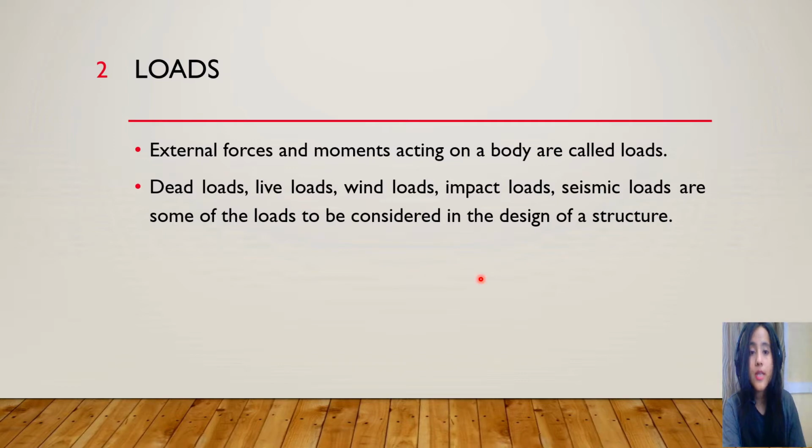So the types of loads acting on a structure, for buildings and other structures, can be broadly classified as vertical loads, horizontal loads, and longitudinal loads. The vertical loads consist of dead load, live load, and impact load. The horizontal loads comprise wind load and earthquake loads.